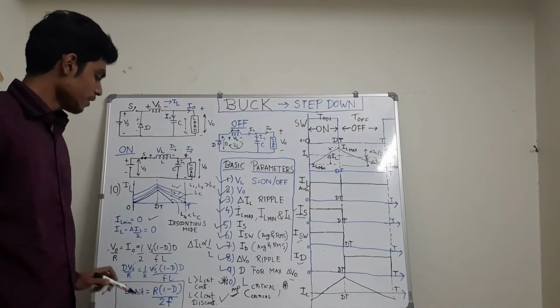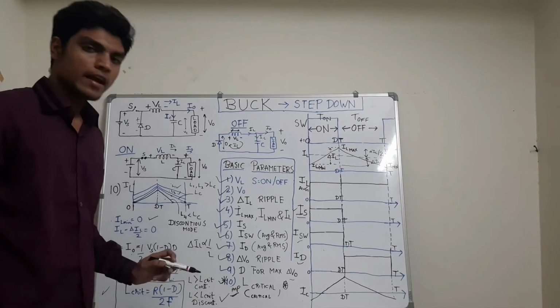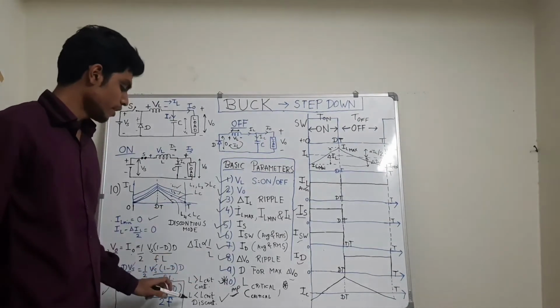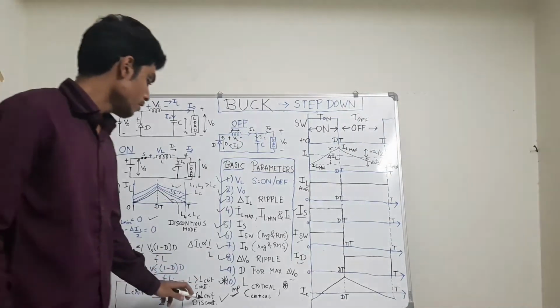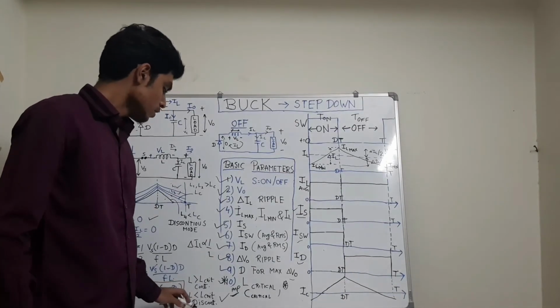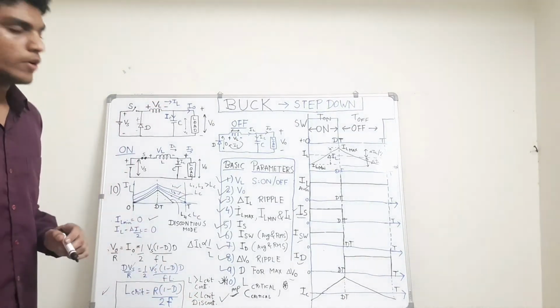It is a very important concept. For L greater than the critical value of inductance, the mode is continuous, and for L less than the critical value of inductance, the mode is discontinuous mode.